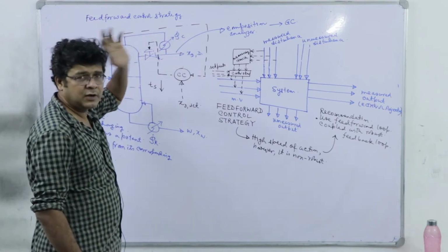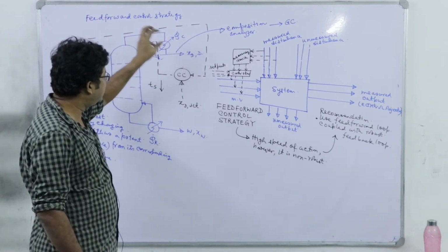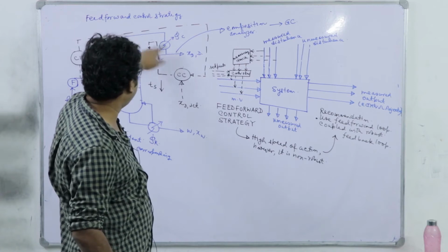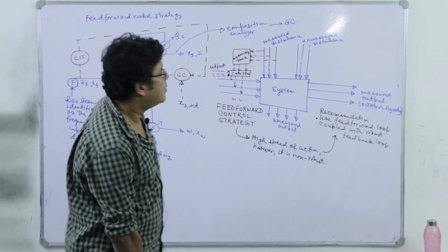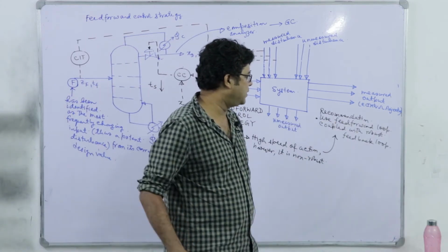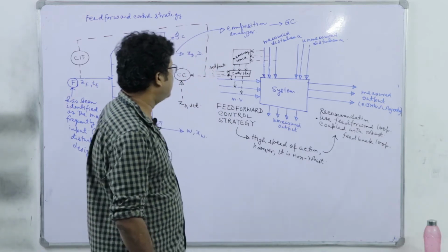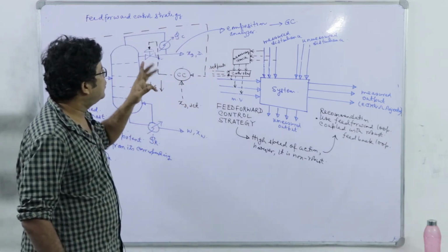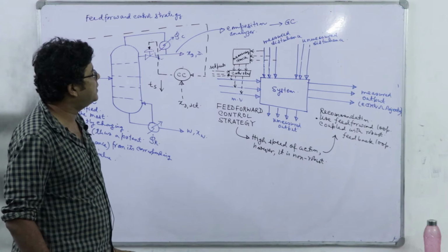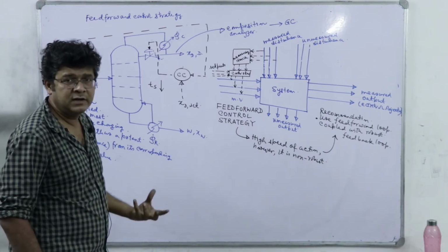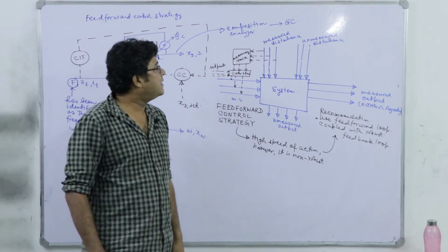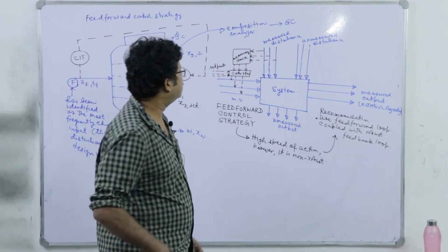So you are producing commercial grade pentane, and for that, your investment to implement a feedback control loop here, I am not talking about feed forward. In feed forward I am not measuring the composition, but that is non-robust. As mentioned, we have to always use it in coupled form with the robust feedback loop. So the thing is, it's totally not economically feasible to use a GC for the production of commercial grade pentane. And that is a problem with all composition analyzers.